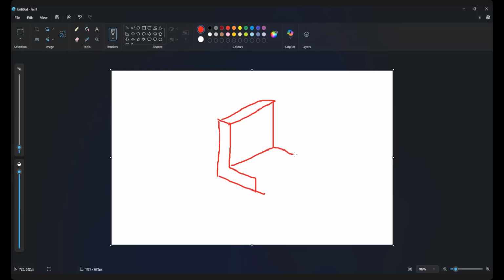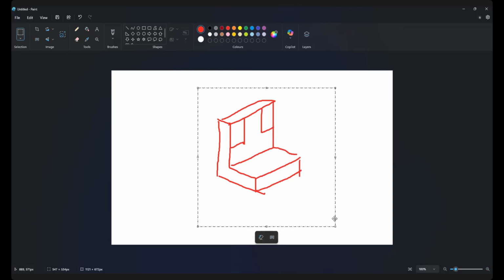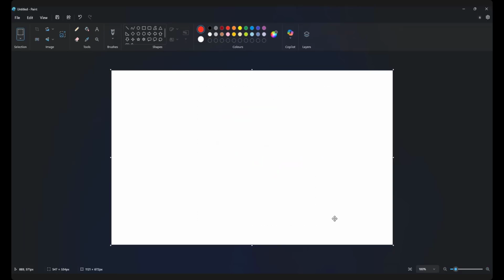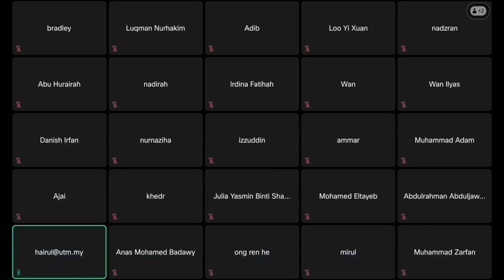For example, in your previous assignment, which I already showed in class, it is on the front plane and you draw it and extrude. Then we can cut out and make a fillet. Then we do feature detailing, either fillet or chamfer and so on, extruded cut holes and so on. So we make detail shaping the product. Sometimes the base profile isn't like this L shape. But if you look at this e-learning,